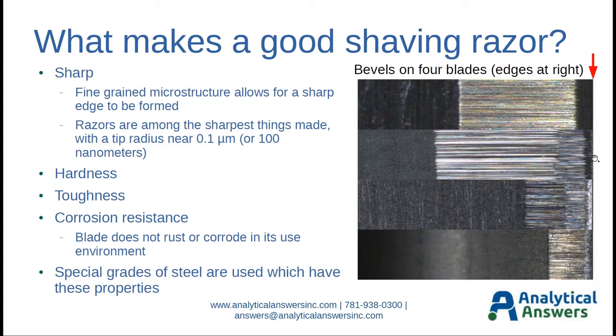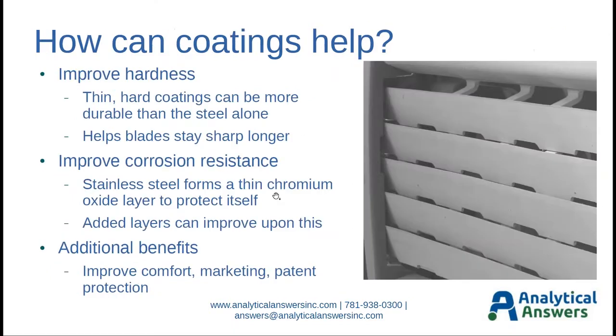And that very long one is a very sharp blade, but it's designed for short duration use, like a scalpel, whereas the very short bevel, which has a lot more metal in it, is going to last longer because that's a shaving razor. And so, of course, depending on exactly the application, you'll have different grinds on these steels.